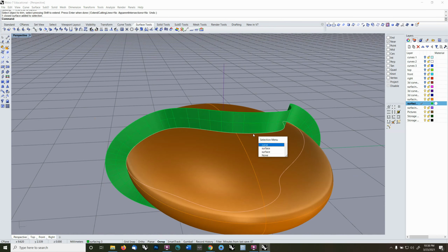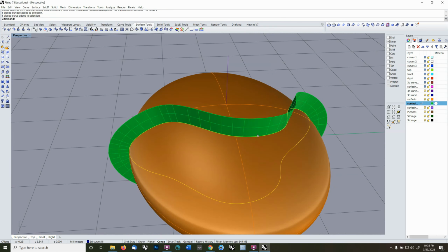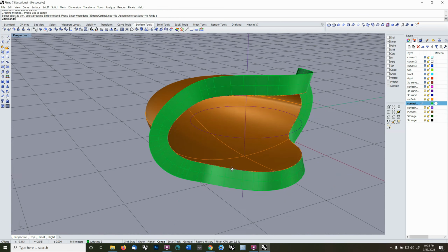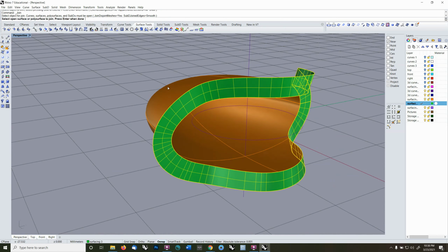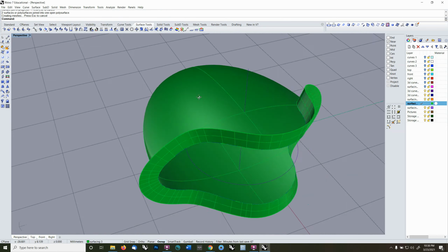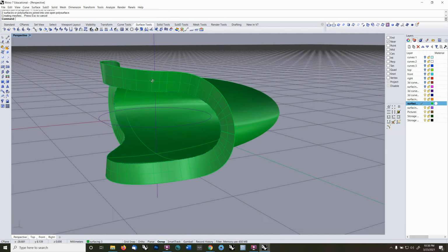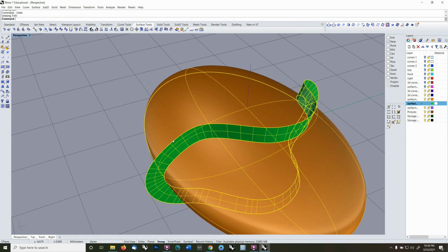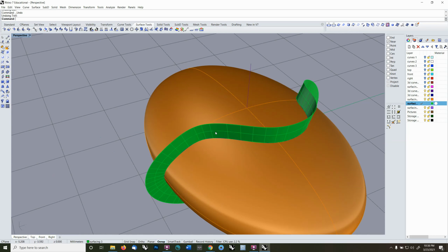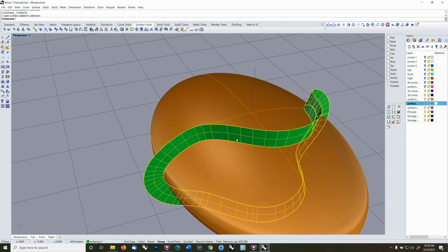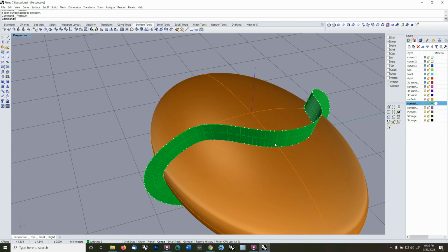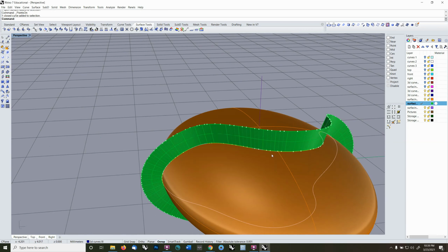Okay. I tried to trim that off and it wouldn't trim because Rhino hates to trim with surfaces. It likes to trim with curves. Okay. You can see how you could have a good time creating forms for jewelry using this. Caveats. When you offset a curve, when you project a curve, you get a very dense curve. Okay. When you extrude normal to surface, you get an even more complicated surface than you had in the curve.